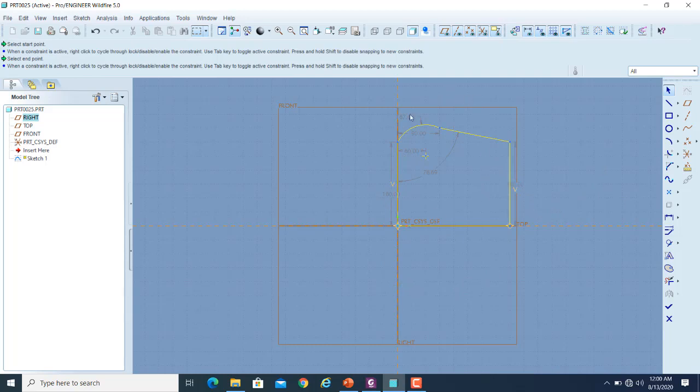So methodology will remain the same. Normally when you make a sketch, it puts default dimensions along those entities, and the color of those dimensions are a little bit dull, blunt color में होंगे. They are called weak dimensions. So weak dimension means that during the sketch, you can change those dimensions. Like for example, if I select this one, double click on that, and I change the value, let me convert it to a round figure of 65, for example.